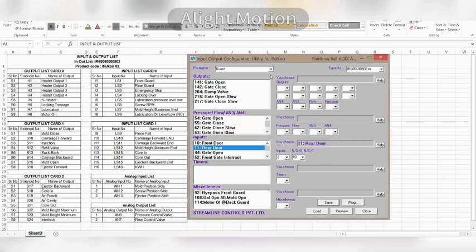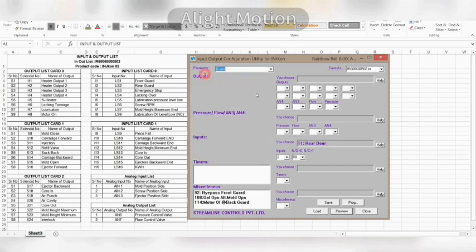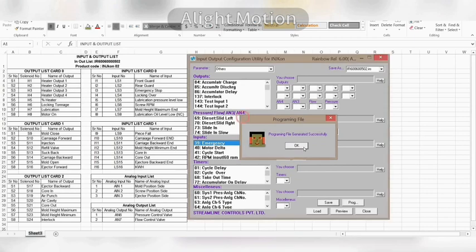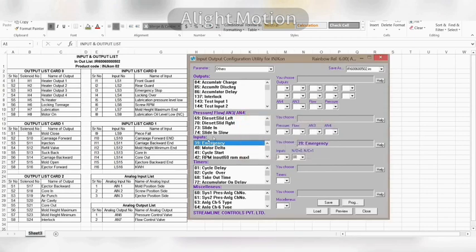And an example of emergency stop. We have number 3 input as emergency stop in the wiring list. Our emergency stop is an extra parameter, so in the parameter, we will select others. In that, in inputs, in emergency, number 3 input is defined with NO0. After the input is defined, save it. So this was our inputs program by sequence programming. Similarly, we have to define the inputs by selecting all the parameters given in the wiring list.